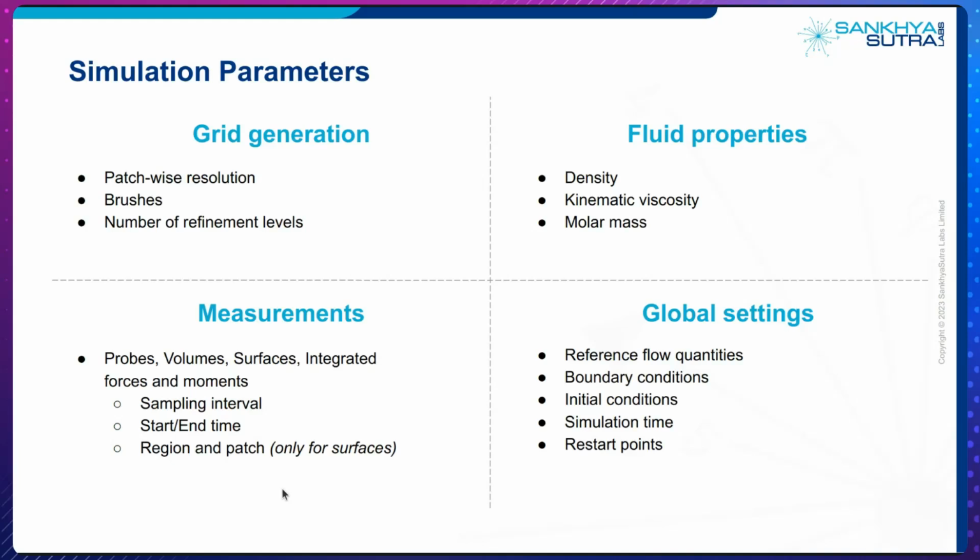And the final thing that you have to do, and this is optional, is that you set up something called restart points. Restart points basically let you save the state of your simulation at certain intervals, and whenever you have to stop the simulation and restart it, you can use the last saved point instead of starting your simulation from scratch. So this will let you save a lot of computational resources as well.